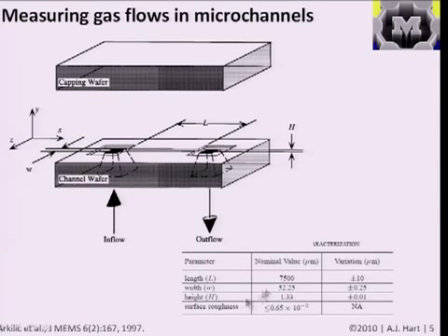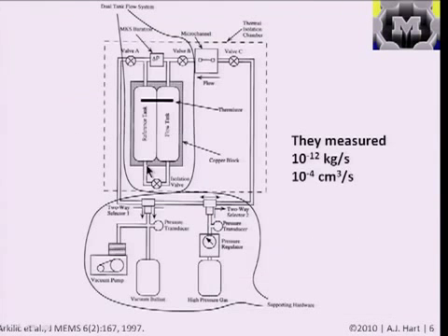So in this case, their nominal value of height was about 1.33 microns, and you can see they had very little variation. So they made sure they had a fairly uniform etch of their top surface layer along the channel, and that let them use just the simple pipe models that we discussed, albeit adapted for a rectangular cross-section, to describe this behavior.